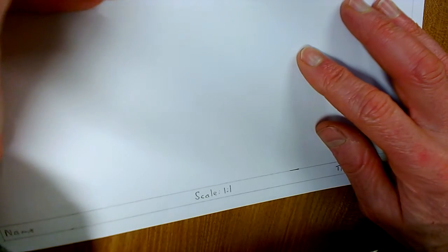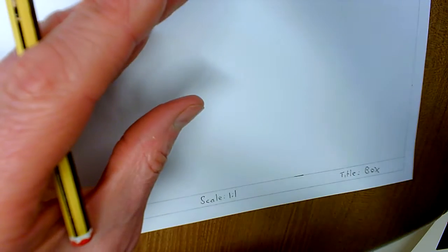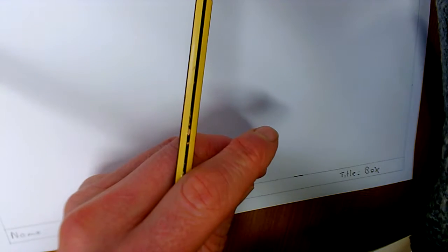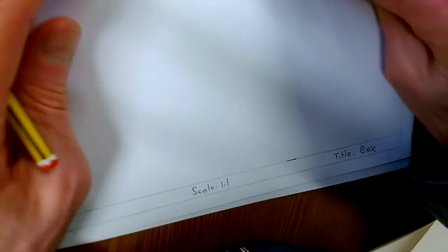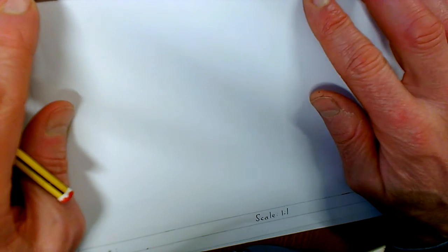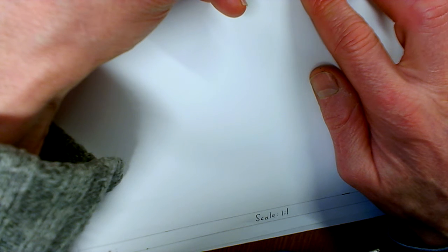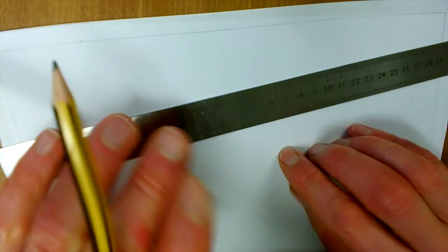So we're going to start up here with our plan view. Remember our plan view is looking from above, looking down on it, a bird's eye view. I know the width of it is 45 and the depth is 40, so it's 45 by 40. Top of the page, centrally. What you could do, again, is measure the width of your page, roughly find the centre, which is around about there, and start there and then split the lines. So they just start at the top of the page. We all start with our plan view.